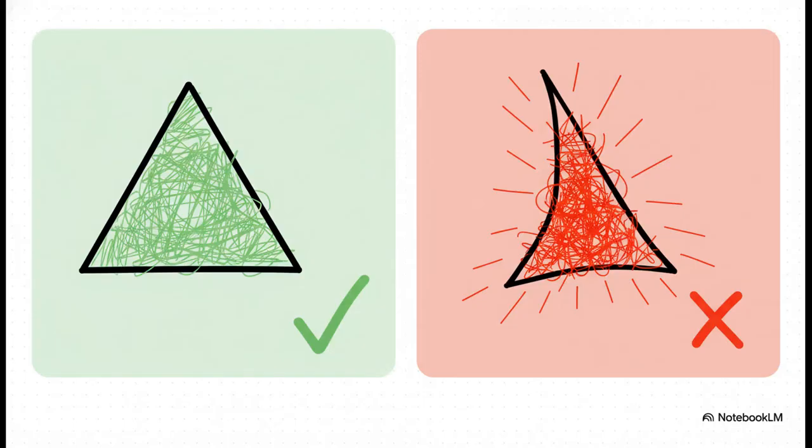And just look at the difference here. On the left, a perfect element. The solver's internal math loves this. It works perfectly. But on the right, you've got this slivered triangle. This thing is a solver's worst nightmare. The math required to map this real, ugly shape back to a perfect reference shape becomes incredibly unstable. And that instability just magnifies tiny numerical errors until they explode and completely wreck your solution.